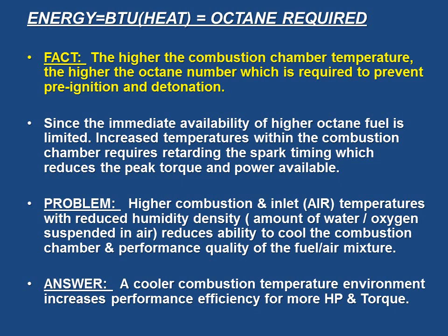The last of all is that in your carbureted racing situations, in your carburetor, unless you have a really good carburetor specialist who can sense the air and the humidity along with the oxygenation you're putting in, you're going to be lowering your BTU ratio. It's a real problem. So stick with the fuel that works and the additive package that's best. And once it's set, don't be monkeying with it, because if you get too lean, it could be a problem.